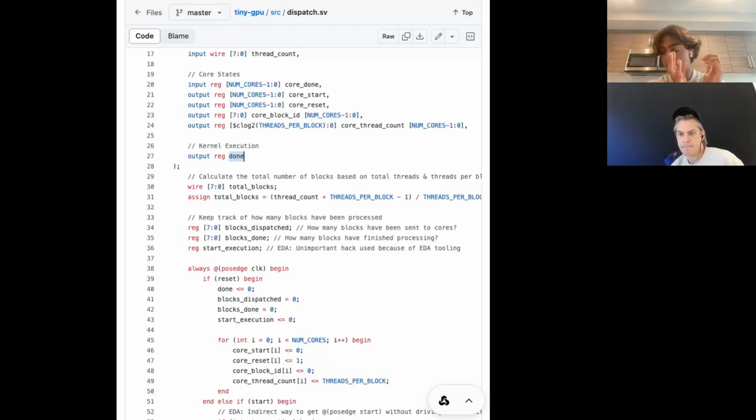It gets outputted into the layout, and that's in the form of a GDS2 file, which just happens to be the file format specifying all the metal layers to send to a foundry. And then you do a final comparison called a layout versus schematic, which just makes sure that this final layout you got after tons of optimization is actually logically equivalent to your original design. And then you can submit that layout to like a foundry.